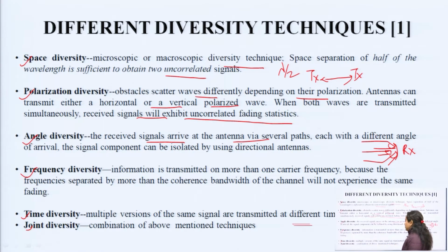Another one is the frequency diversity. In this, the information is transmitted on more than one carrier frequency, because the frequency separated by more than the coherence bandwidth of the channel will not experience the same fading. So, that is the frequency diversity.